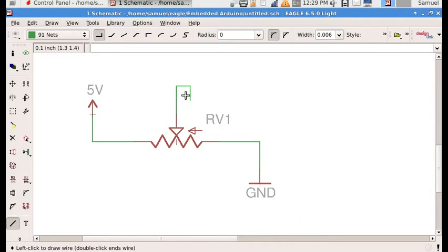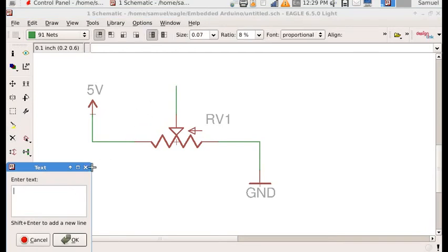here. So basically this divides the voltage between 5 volts and ground whenever this arrow is moved. If you move it all the way over to the 5 volt side, it'll read 5 volts. That's like if you move the joystick all the way to the right. And if you move all the way to the left, it'll go to ground. I believe it's right and left, I'm not sure, just giving an example. But when it's neutral, in the center, it'll read 2.5 volts. So when that is right there, this actually reads 2.5 volts.